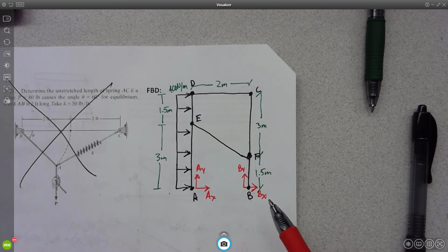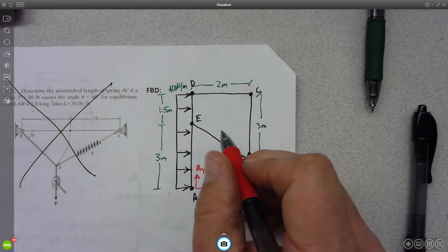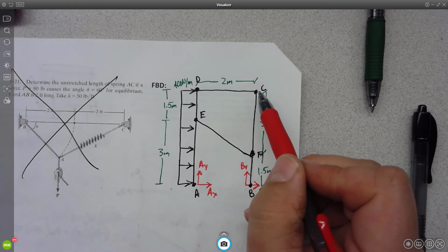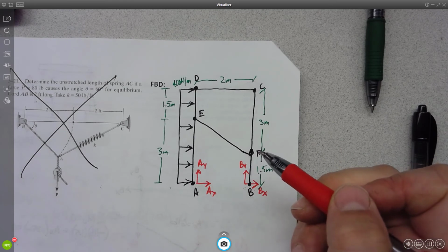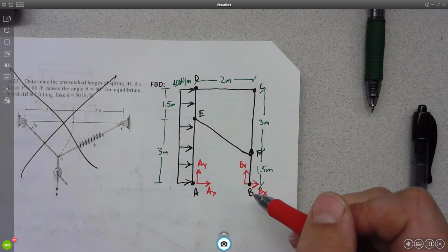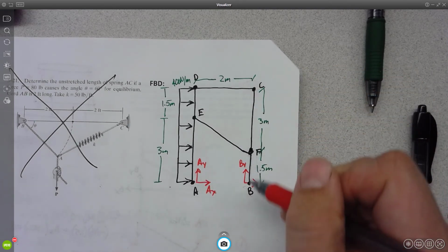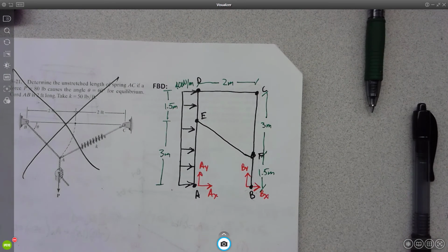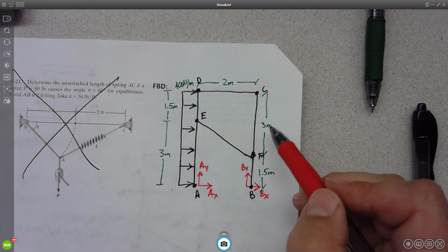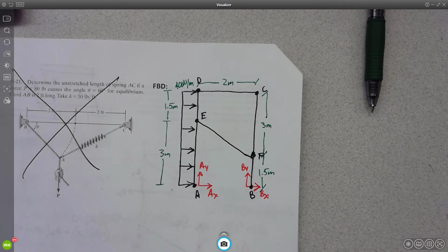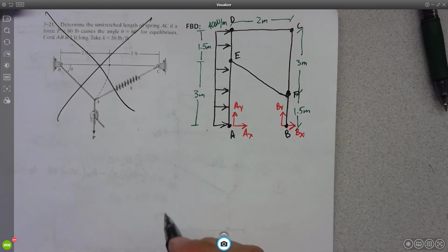So where are my two force members? Okay, E to F. This is a two force member. DC and CF. Sorry, CB is one continuous. Right, C to B is one continuous member. So like the two sides are continuous, and then there's just two struts that go across. All right, so it looks like EF is a two force and DC is a two force. Okay. So how do we proceed? Split it up. Draw individual free body diagrams. So let's start with DEA.